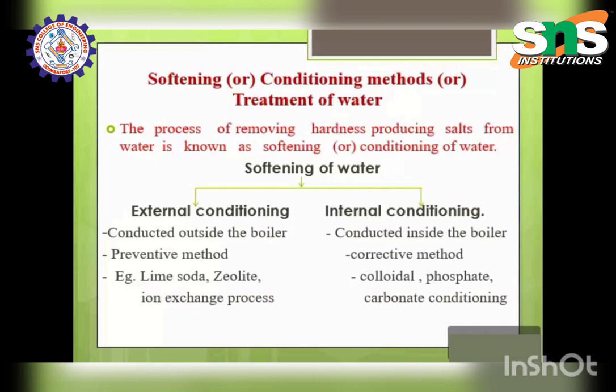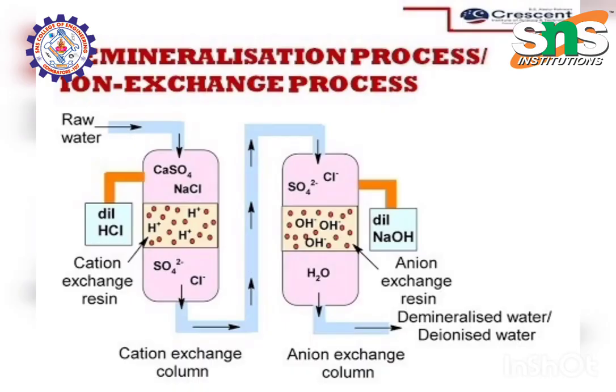In the anion exchanger, the resins containing basic functional groups like NH2, hydroxyl group, etc., remove the anions present in the hot water. Examples for anion exchangers are cross-linked quaternary ammonium salts or urea formaldehyde. It is represented by ROH.